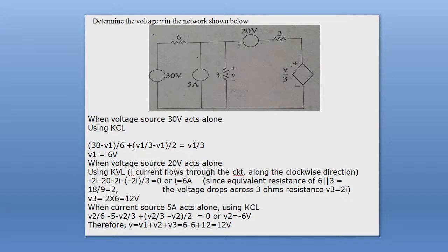On the other hand, we can replace independent sources by their internal resistances. Everyone keep in mind that to solve a circuit theory problem either using superposition or Thevenin's, whatever I will discuss later on, dependent sources will always be present in our circuit, but we can replace independent sources by their internal resistances. Any doubt?